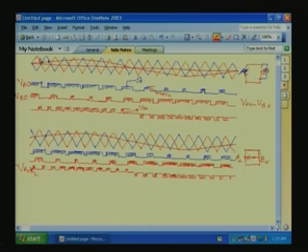Now, if we sum these two voltages, that voltage will have a shape like this. To get a feeling of the harmonics of the current waveform, instead of summing the current waveforms, you can sum these two voltage waveforms. This may be the replica of the voltage waveform appearing across the two transformer secondaries and reflected on the primary.